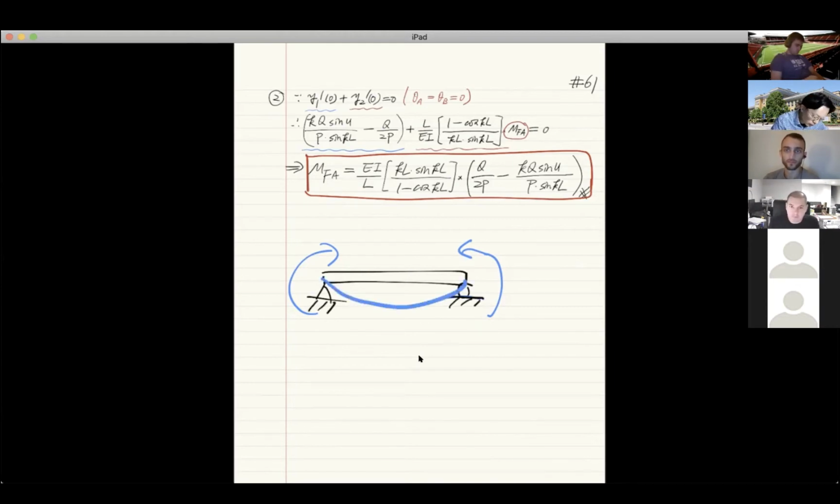And the reason why you have to consider this P is because the second order effects, right? So that means you have a second order effect somewhere here. That's why the deflection due to existing moments, that's what caused the second moment or the secondary moment effects. Now, if you don't have this force considered, you're not going to find the second moment effects. You'll just be finding just the primary order moment.